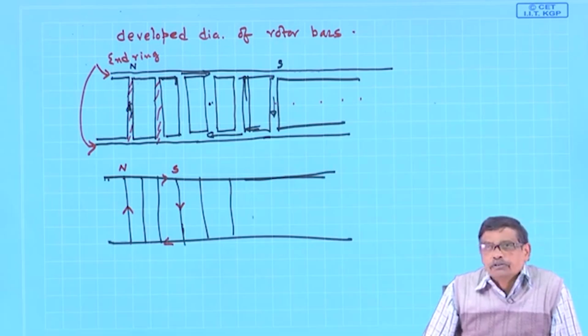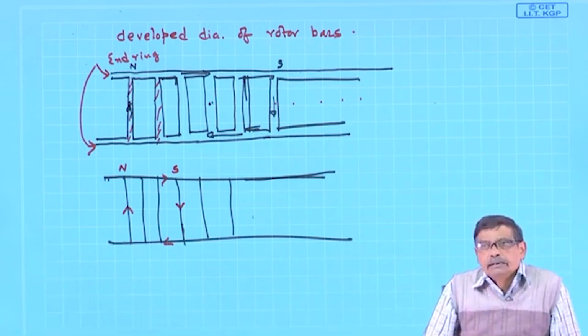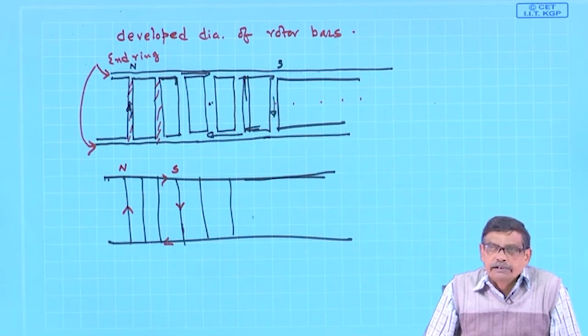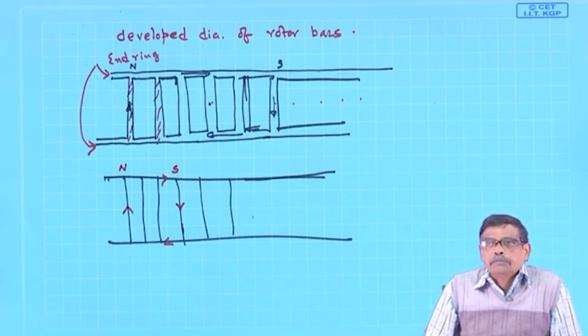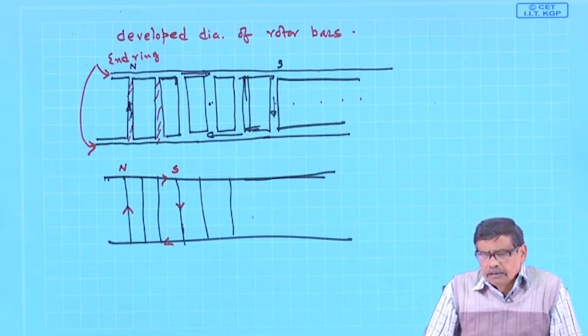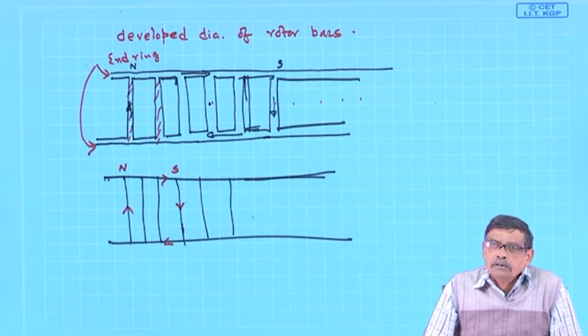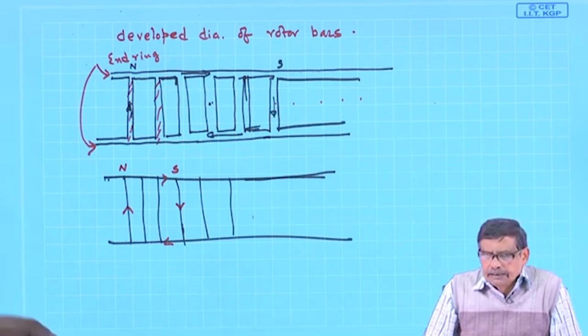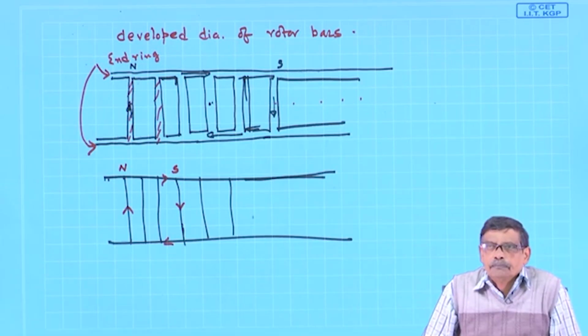But it is possible, which I indicated while discussing my winding layouts, that sometimes you use the same winding which is wound for say 4 poles and reconnect the winding groups such that it will produce 2 poles. That is the new thing I am telling now.